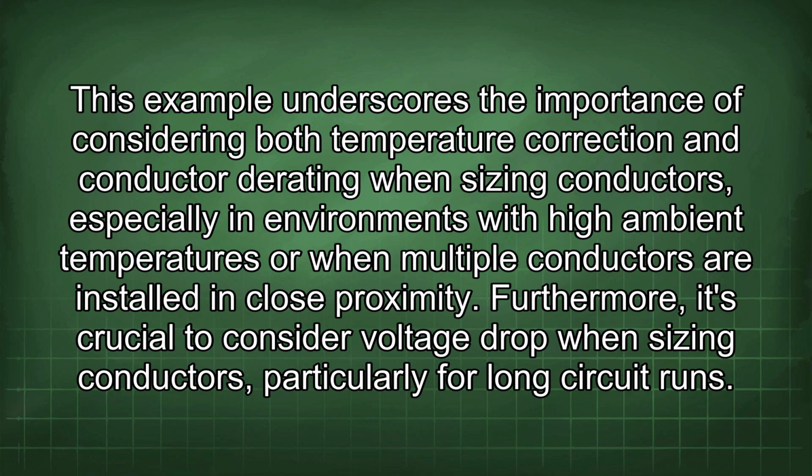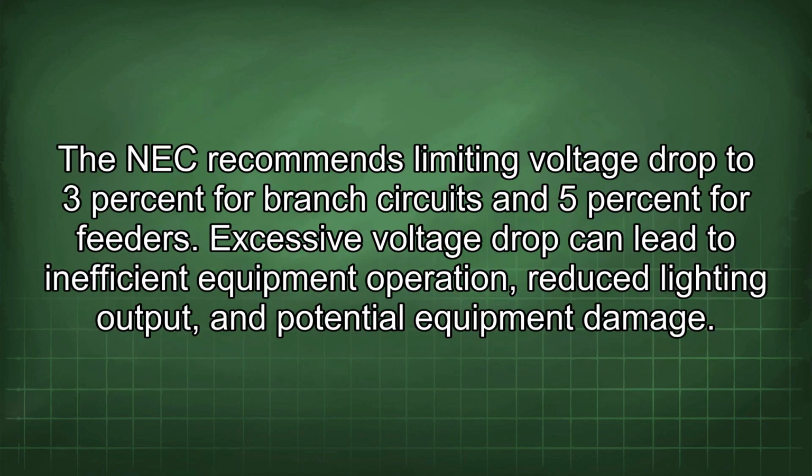Furthermore, it's crucial to consider voltage drop when sizing conductors, particularly for long circuit runs. The NEC recommends limiting voltage drop to 3% for branch circuits and 5% for feeders. Excessive voltage drop can lead to inefficient equipment operation, reduced lighting output, and potential equipment damage.